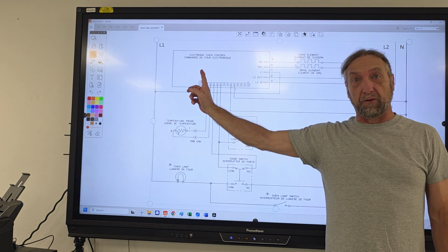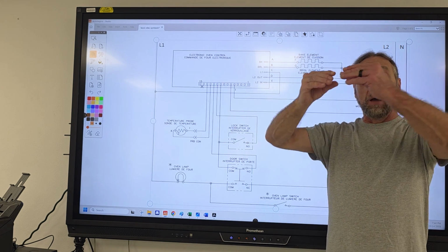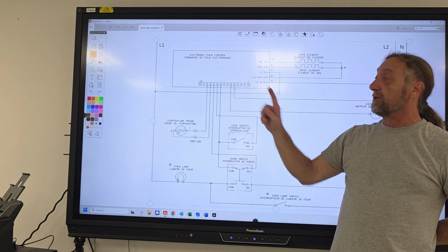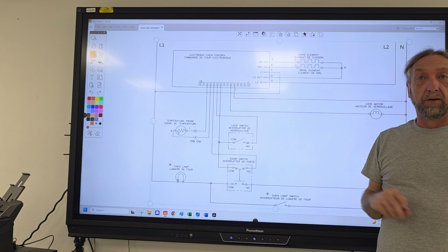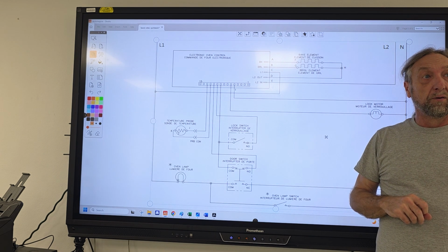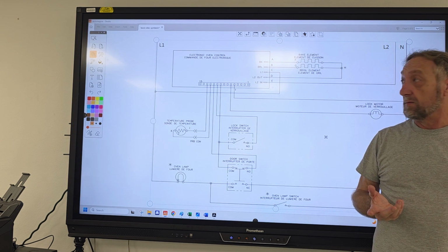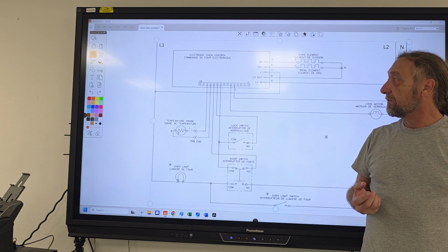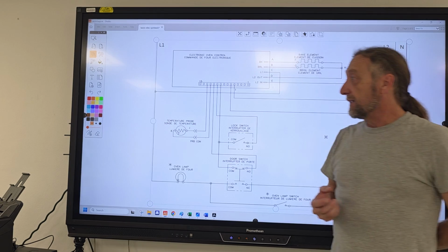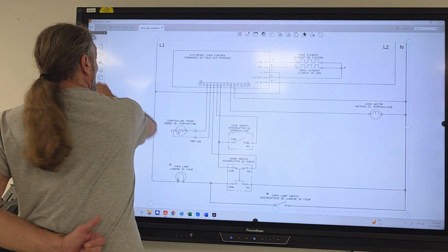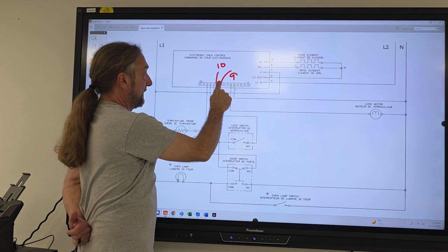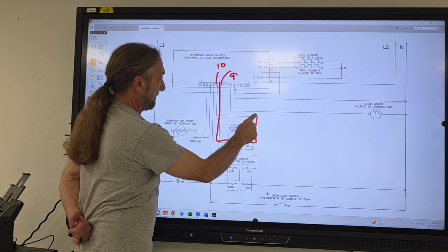This has the ability for 15 wires to be connected, but we have this big long plug, and there are no wires here, no wires here, and no wires there. Number 9. Just number 9? It's one line to the 9 and 10. Yeah. Then if I put my meter lead on pin 9 and 10, that'll go like this and check the switch.